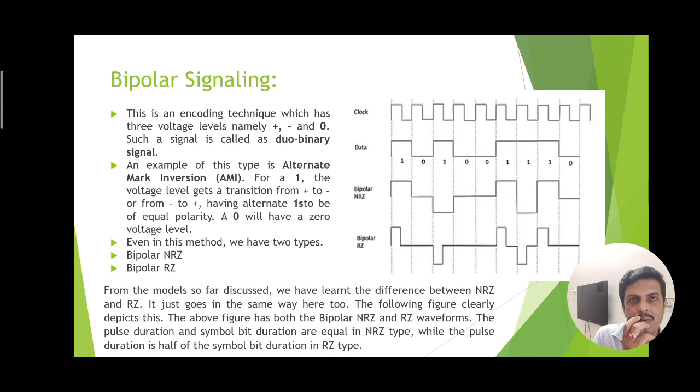As we already have started with the line coding, let us recap why line coding is required, because pulse code modulation is not sufficient to represent the signal. The pulse code modulated binary bits, which are representing logic high for 5 volt and logic 0 for 0 volt, are not sufficient when they are propagating through the channel, because they are facing several problems: the problem of recovery of clock pulses, and the problem of degradation over the channel because of less noise immunity.